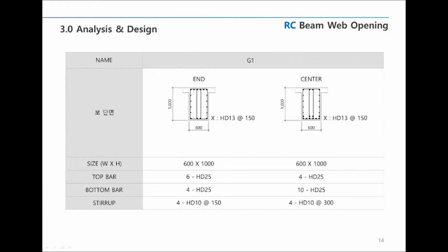Because the conditions are set to get the appropriate reinforcement plans when locating an opening in the beam, always keep in mind that the girder size is bigger compared to the column intervals, and the load condition is not normal.